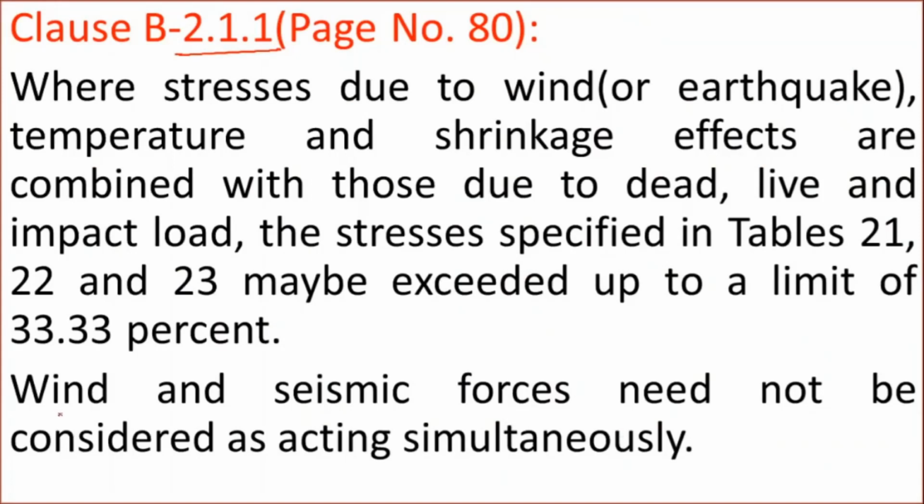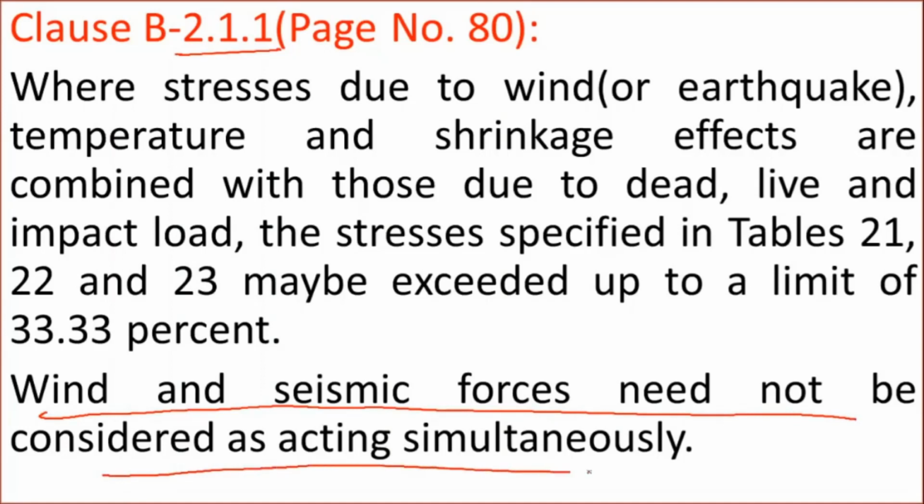Then it is also saying that the wind and seismic forces need not be considered as acting simultaneously. The probability of both wind and seismic forces occurring simultaneously is very rare, very rare.